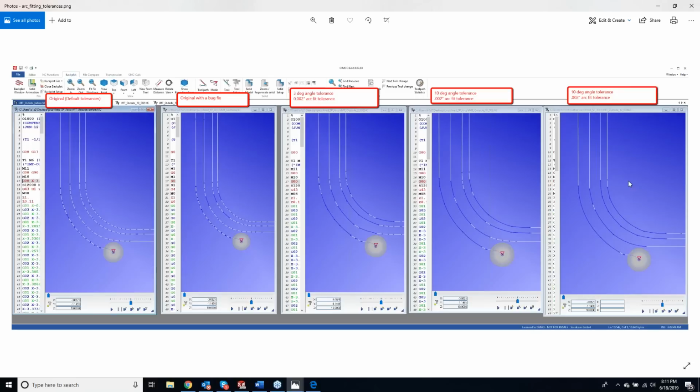And yeah, definitely. And also what it will do is shorten up that G code for you guys. So doing a G2 move over this long arc here is going to be one or two lines of code, where over here, I guess that's kind of what you were just saying, Greg, you got multiple lines of code just to get around that one arc.